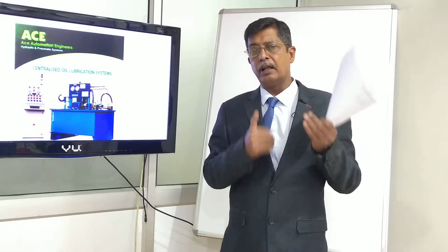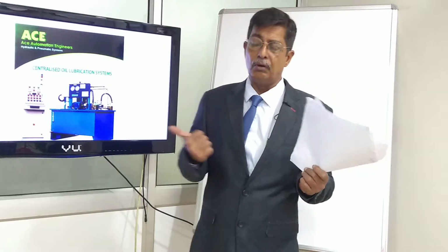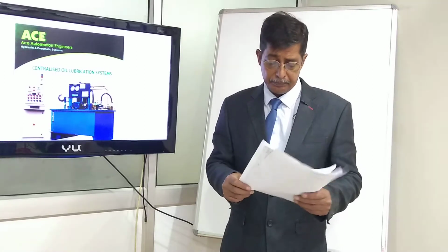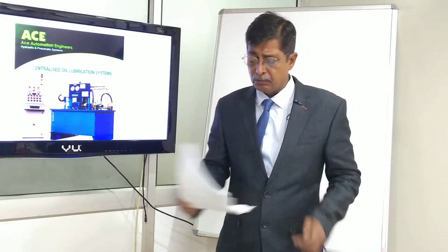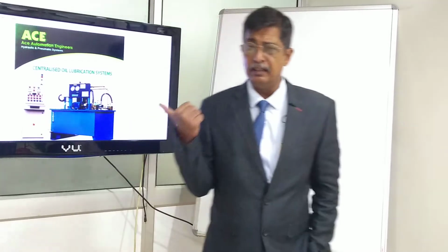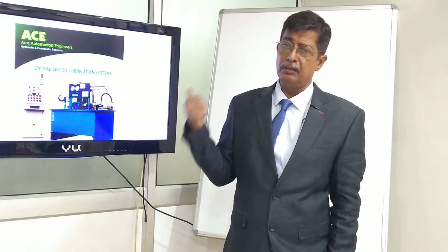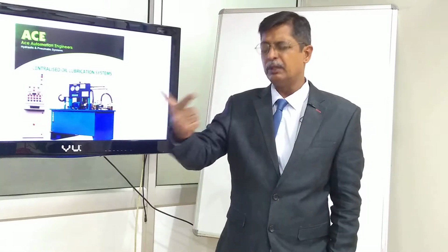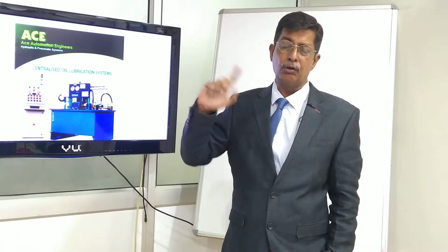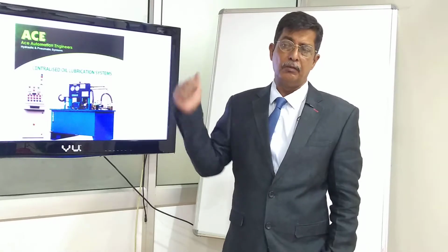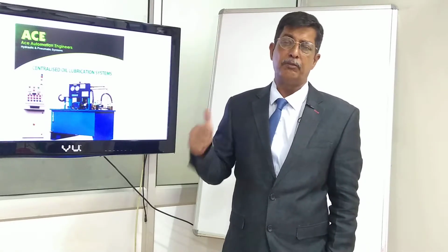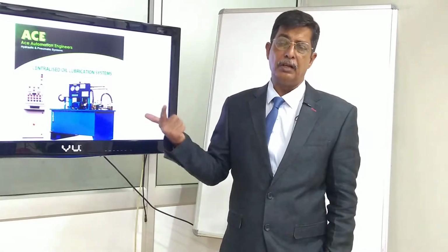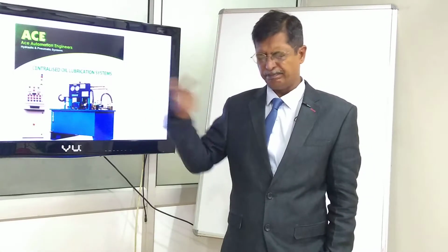So just taking care of these three primary issues. One, we have a standby pump and an auto changeover system where the moment the one pump fails, we switch to the second pump. Second, a good and efficient lubrication oil cooling system. And third, two filters, one working, one standby, and an alarm system to tell us when the filter is going to get choked.